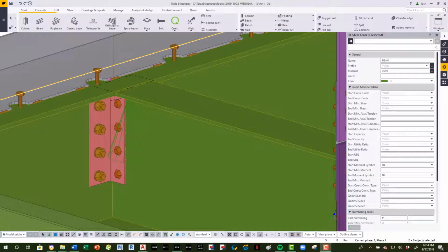The last thing I want to touch on here is typically we see a reduction of bolts of 1 to 1.5 bolts per ton. So if you have a 1,000-ton project, you could see about 1,000 to 1,500 fewer bolts, and of course 2 to 3,000 fewer holes to drill, punch, or cut. Add that up job after job, and the results are very impressive. Now let's get into workflow.